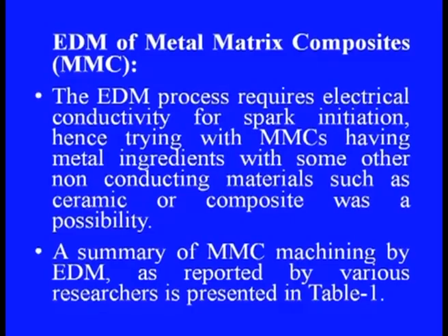Then let us look at the possibilities of electric discharge machining of metal matrix composites, which are also commonly known as MMCs. The EDM process requires electrical conductivity for spark initiation. Hence, trying with MMCs having metal ingredients with some other non-conducting materials such as ceramics or composites was a possibility. A summary of machining of MMCs by EDM is shown in the following table, which we will see shortly.